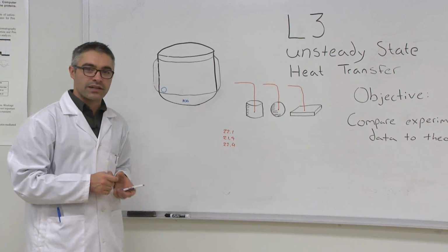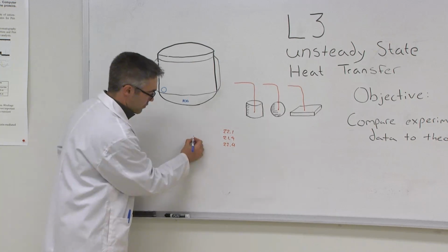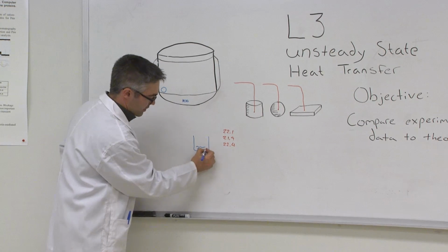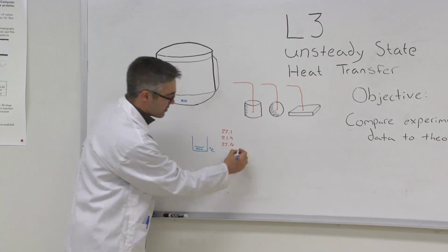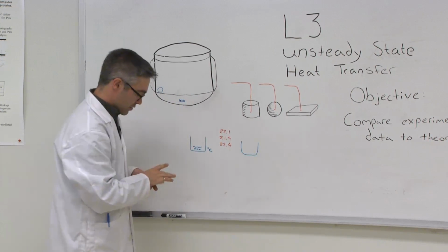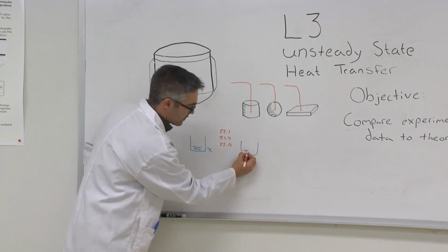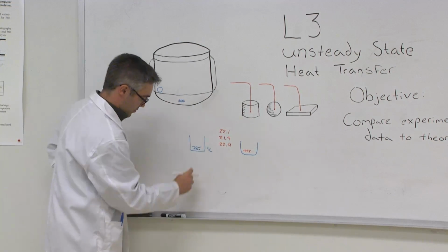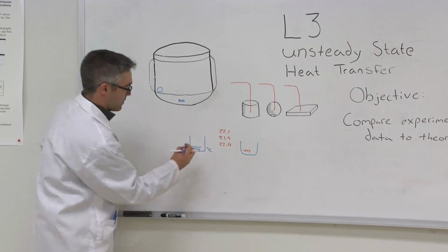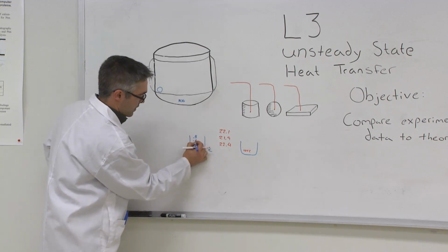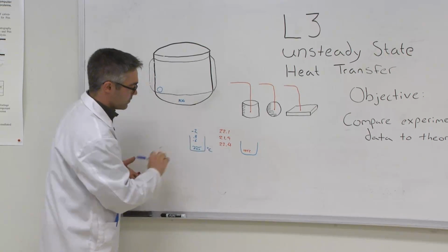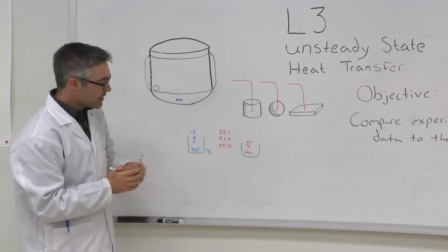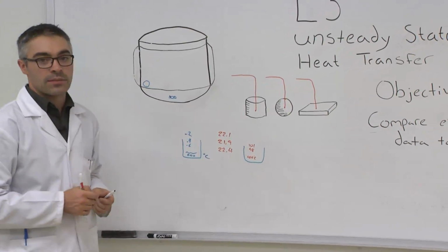The way that we're going to calibrate them is by immersing the thermocouples into a bath of ice water, which we can assume will be 0 degrees Celsius, and boiling water, which we assume can be 100 degrees Celsius. Now, any offset from these values, for instance, 0.4, 0.6, -2, and 101, 98, you can calibrate each thermocouple by basing it off of these absolute measurements.